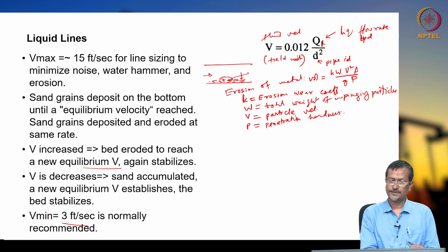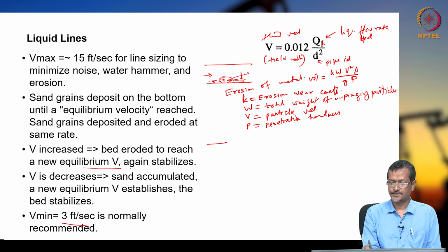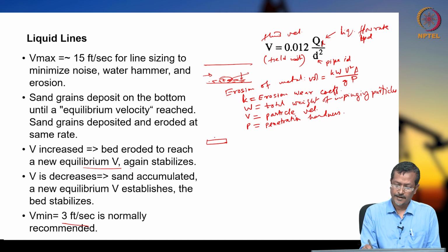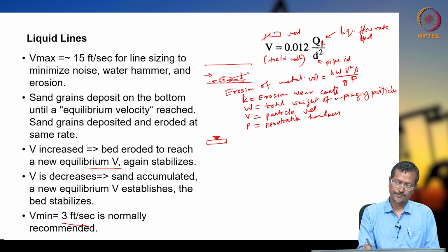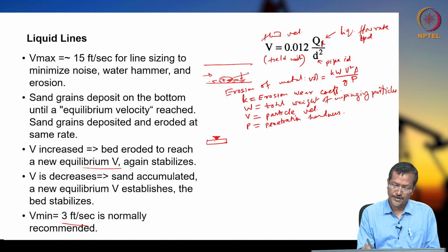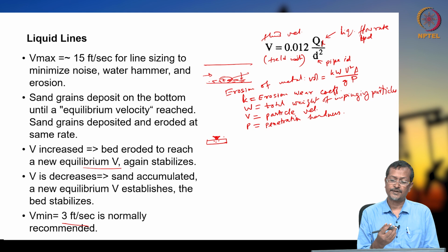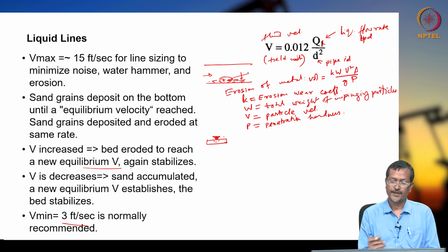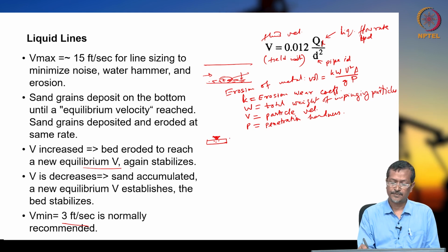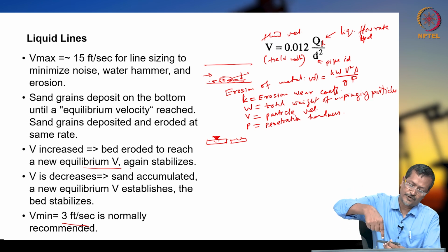So, hardness is how hard the metal is, and this is how it is tested. They take one specimen, one metal, and a small diamond-shaped or triangular-shaped, strong solid indenter, and try to push it down. They measure how much indentation happens, and that shows how much hardness there is. Sometimes the tip is diamond shaped, sometimes circular.